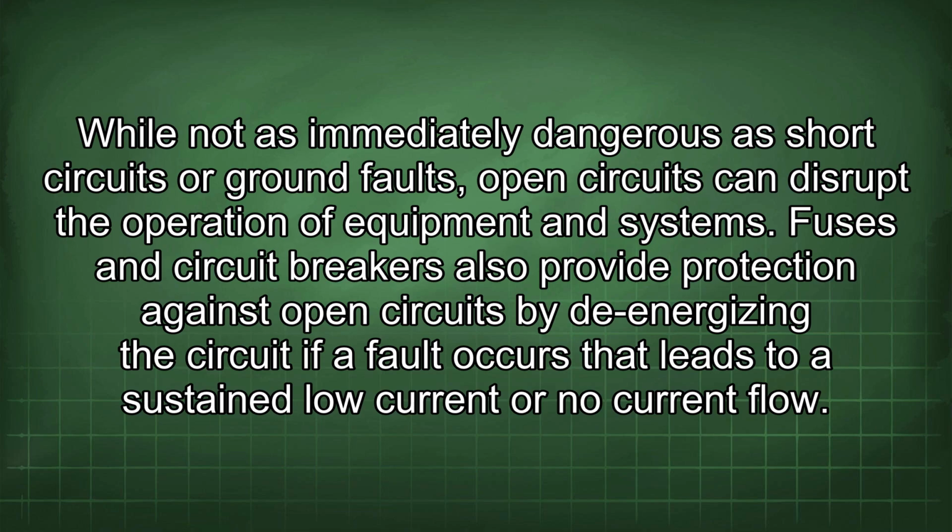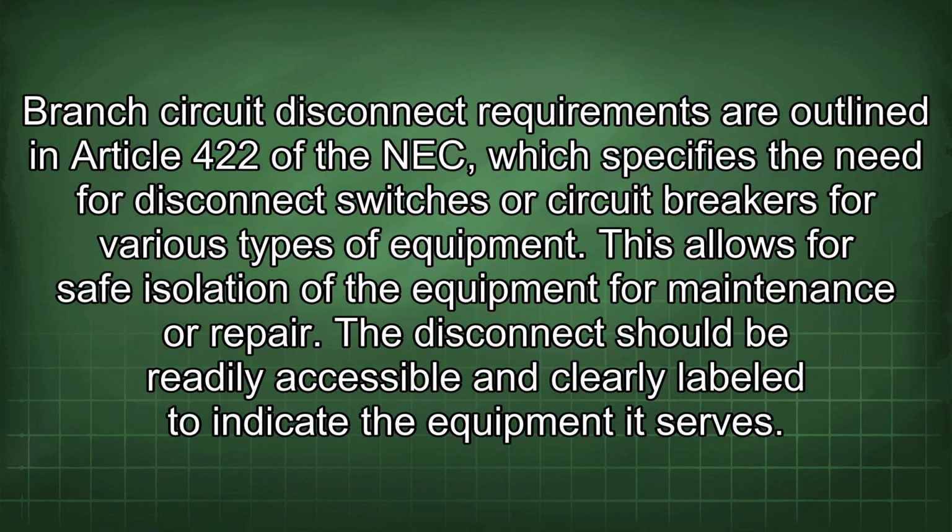Fuses and circuit breakers also provide protection against open circuits by de-energizing the circuit if a fault occurs that leads to a sustained low current or no current flow. Branch circuit disconnect requirements are outlined in Article 422 of the NEC, which specifies the need for disconnect switches or circuit breakers for various types of equipment. This allows for safe isolation of the equipment for maintenance or repair. The disconnect should be readily accessible and clearly labeled to indicate the equipment it serves.